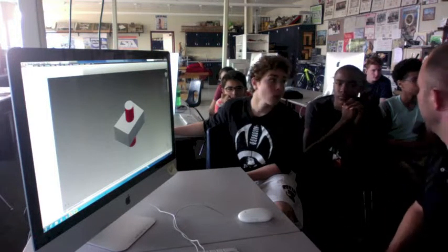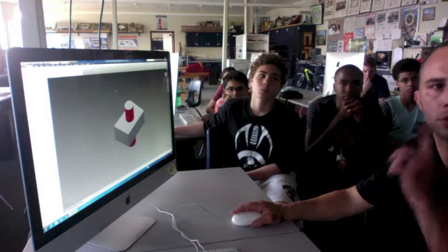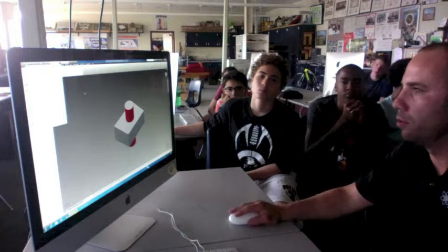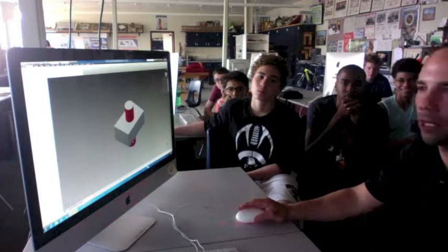And it automatically saves that file type as an IAM. Okay, print something really quick. And then I'm going to go to, that's saved. I'm going to go to File, New. IDW is my drawing file, and I'm going to create it.